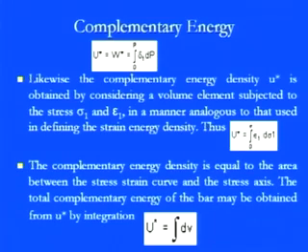So here our main focus for the complementary strain energy is absolutely on what exactly the variation is in the elemental part of the stress, and then what the corresponding changes are in the strain part. So after considering all the small elements where there is a variation in the stress part, we can simply get the U bar by integration. U star is nothing but the integration of all those volumetric parts.